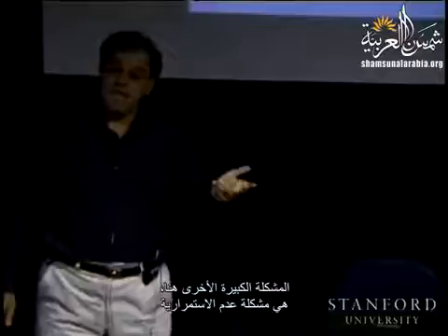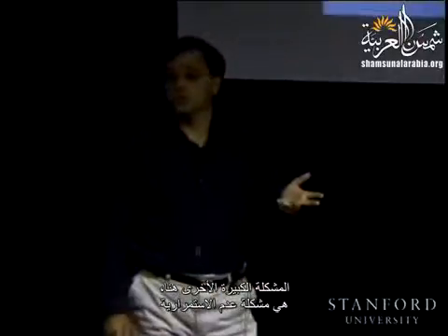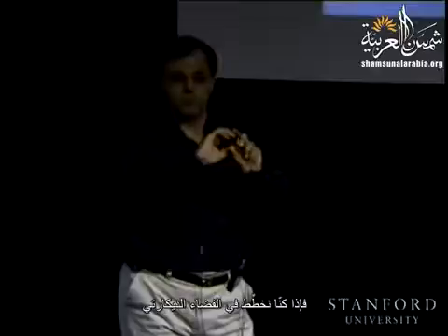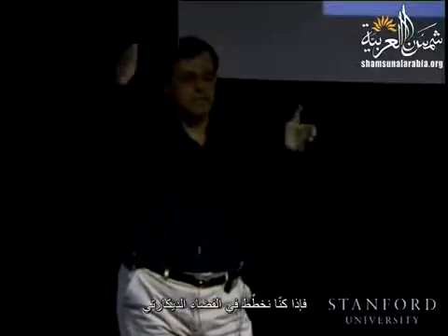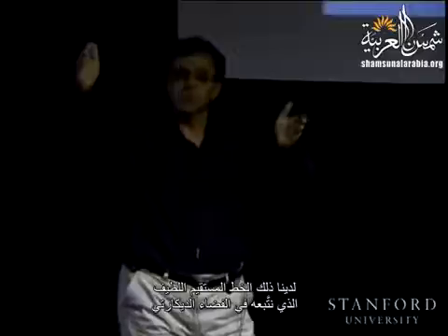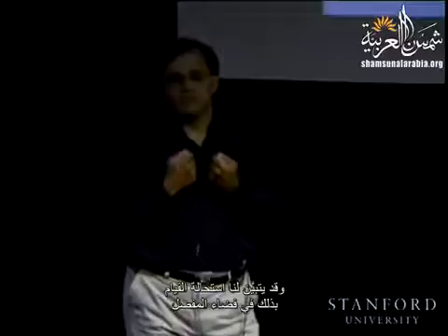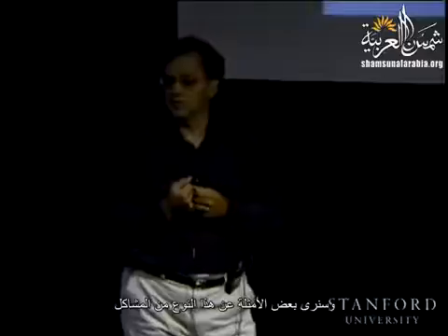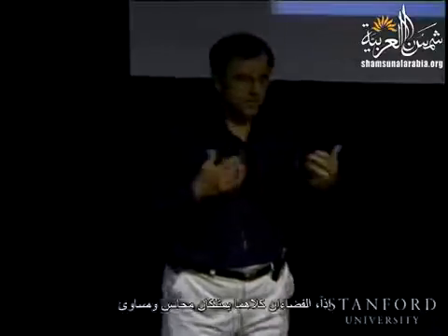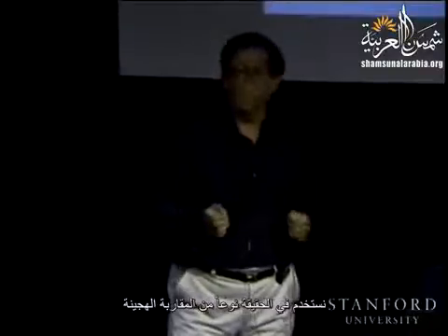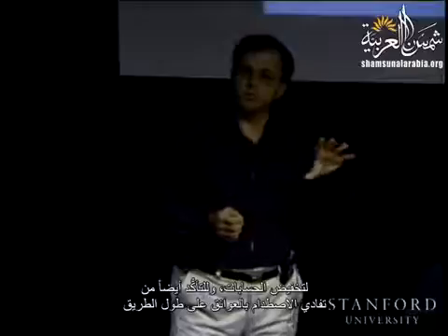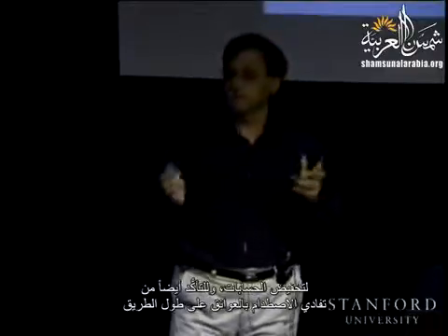And the other major problem is that we have discontinuity problems here. Because if we are planning in Cartesian space, we have our nice straight line that we are following in Cartesian space. We convert to joint space, and it might turn out that it is impossible to do that in joint space. We'll see some examples right now of this kind of problem. So both spaces have pluses and minuses. In reality, you usually use some sort of hybrid approach to limit the computation, but also to make sure that you're not colliding with obstacles along the way.